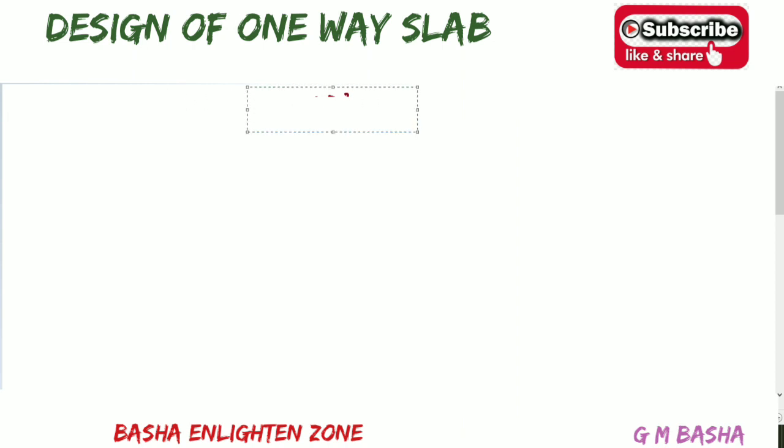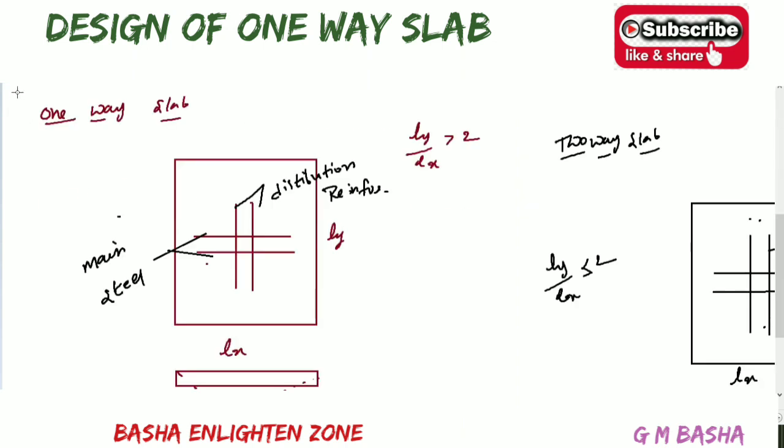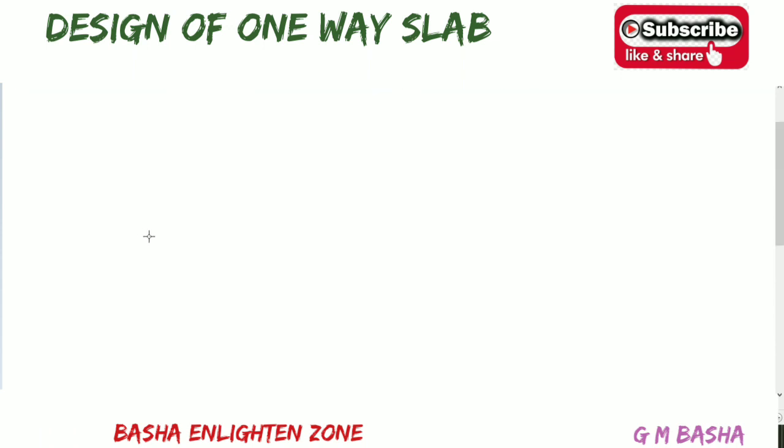For a two way slab, based on whichever moment is higher, we can design the spacing and provide it in both directions. But for the one way slab, we provide distribution reinforcement.